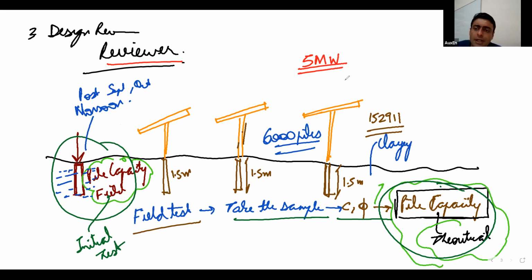So because they become sticky, when these piles were tested for uplift, meaning you try to pull out these piles. Now tell me, I know that you don't know the basics of pile right now, we would be discussing it during our course, but just on the basis of common sense, tell me, if I try to conduct an uplift test on my piles just after the monsoon, when the groundwater table is very high and the soil is very sticky, what do you think will happen? You will get a good uplift capacity. Do we agree or not?